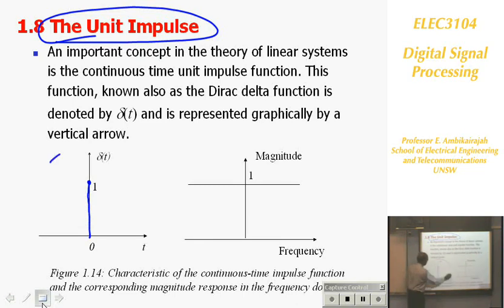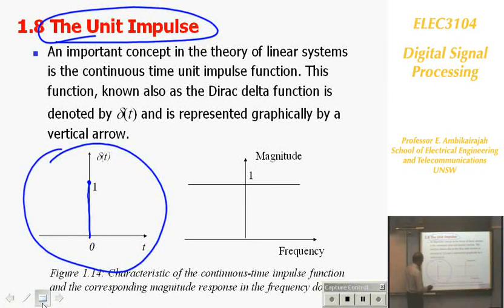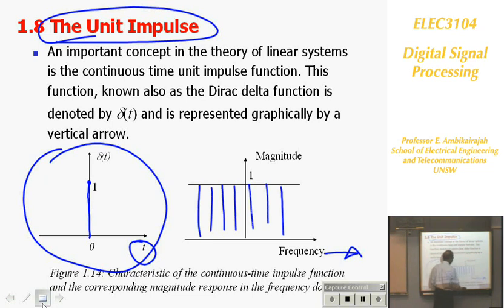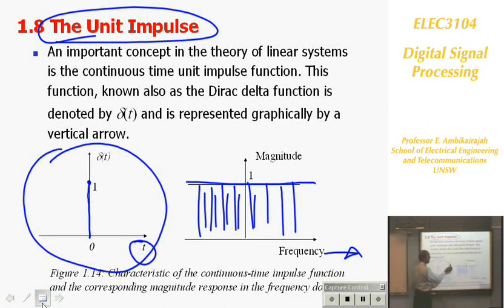If you look at the frequency content of this, so this is the time axis. If you plot the frequency content, the impulse has all the frequencies at equal magnitude. That's why we use impulse for testing a lot of things. It has every frequency you name it, and they all have equal magnitude. So if you want equal magnitude at all frequencies, you need to generate an impulse.